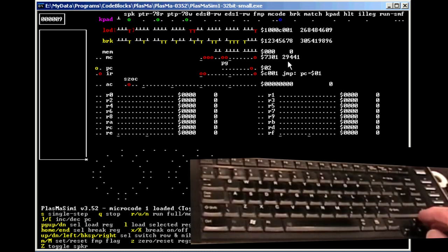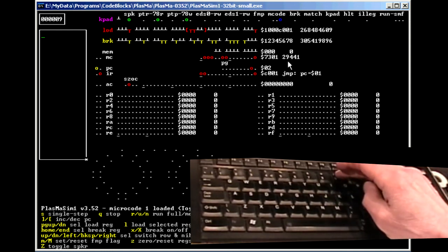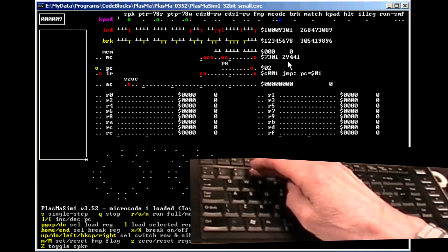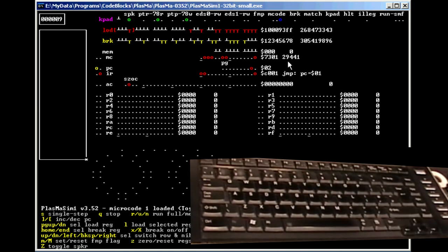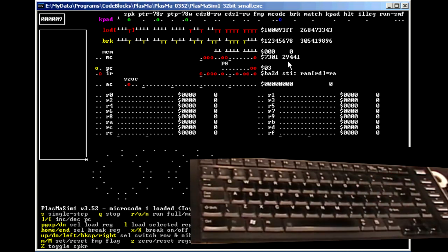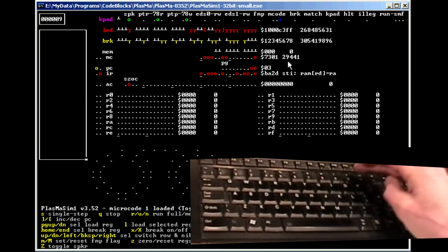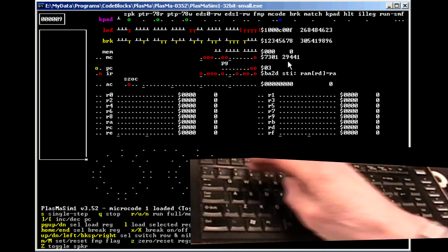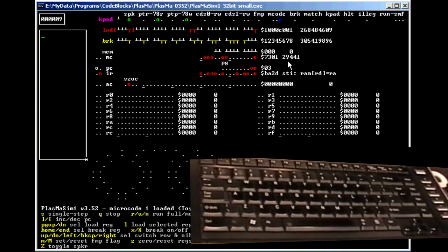So we position the highlight on the load registers. We want 9 for the opcode, 3 for the source register, FF for the special IO memory address, and then load and inc. And now we need to enter the new jump instruction, C001, and load.